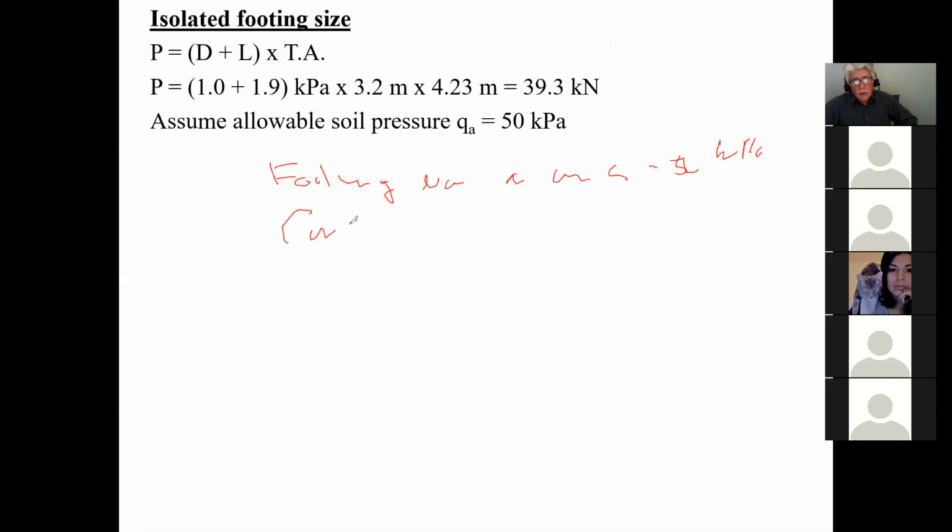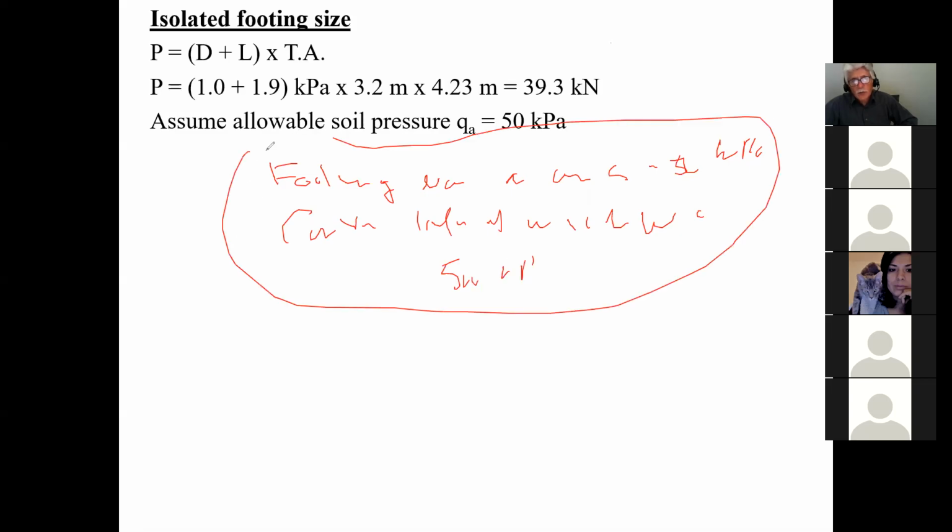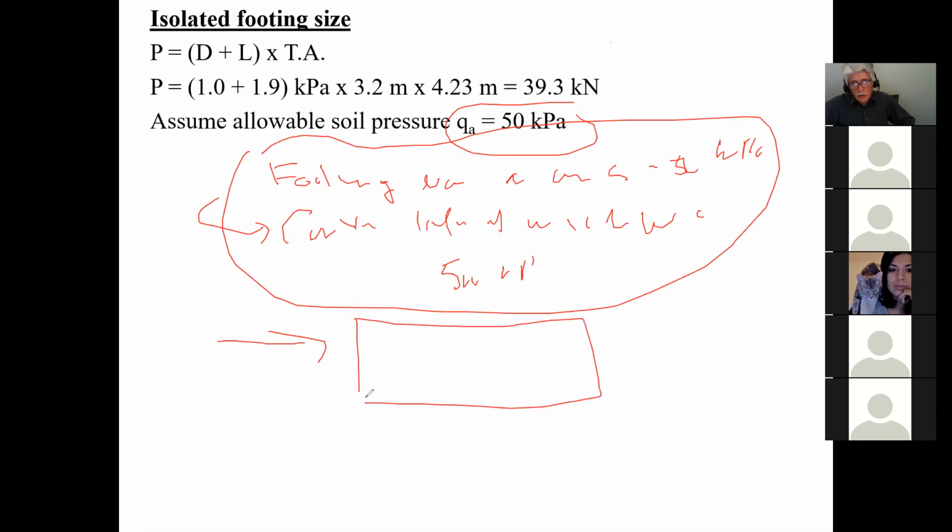Contractor to verify if in-situ soil has at least a bearing capacity of 50 kPa. And that's what we used to put on our drawings. And we figured we covered ourselves because we put the onus on the contractor to make sure that whatever soil condition he encounters at the job site, he has to confirm that our assumption of 50 kPa is good. And that's what everybody was doing until finally one person went to trial and the judge condemned the engineer for doing this. And because of that, this is no longer a good thing to do.